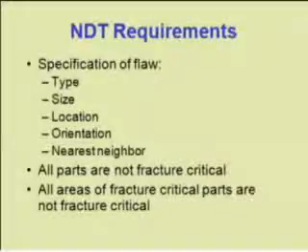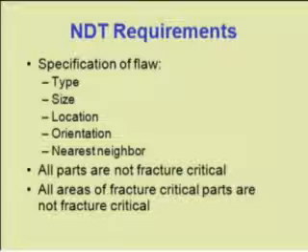Now, in terms of the requirements, what we require as NDT guys is not an easy task for the designer. I must know the type of defect that I'm looking for. I must know the size of it. I must know the location. I must know the orientation. And I must know the nearest neighbor, and that is the proximity of one crack to the next crack. That's the basis for all acceptance criteria before you come to the NDT guy. You must know the answers to these problems.